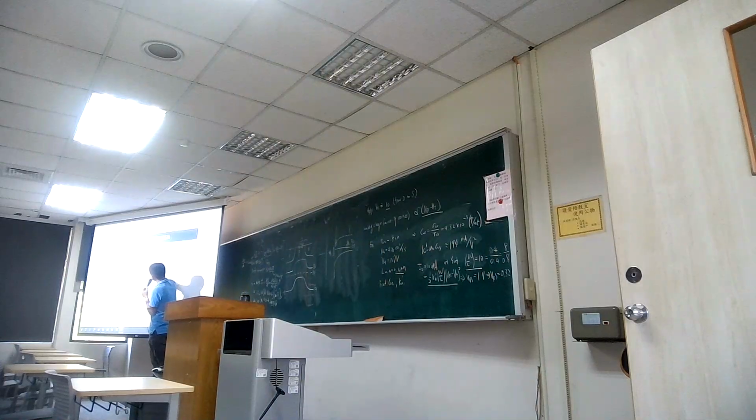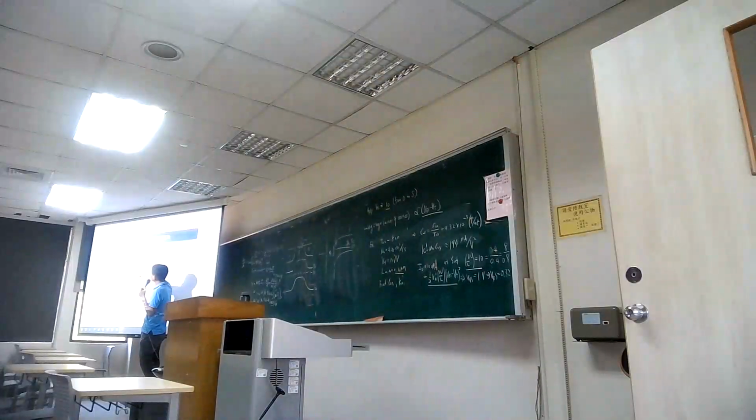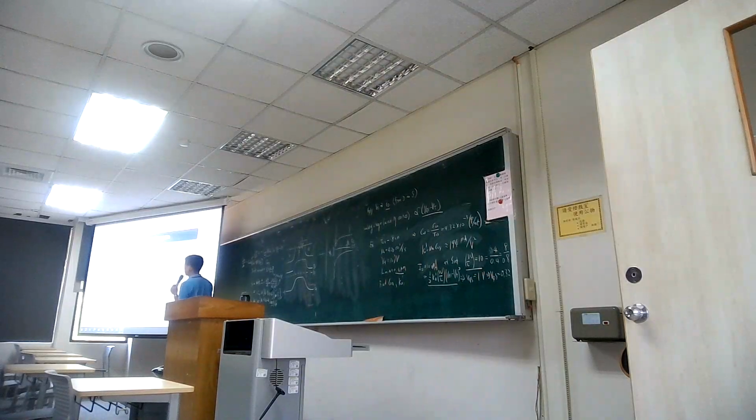We call it the surface potential, phi s equals 2 phi f. So you get it without any drain voltage. That is, with the depletion we get the inversion layer, which is phi surface equals 2 phi f. And then at non-equilibrium, you get an additional reverse bias at the drain.